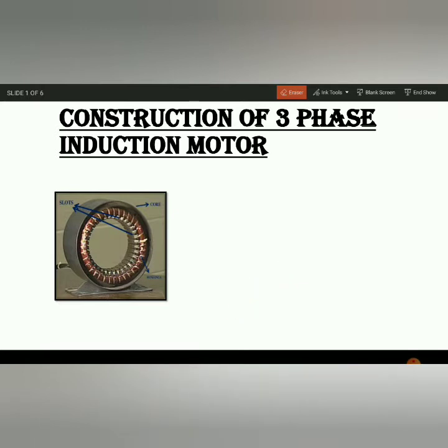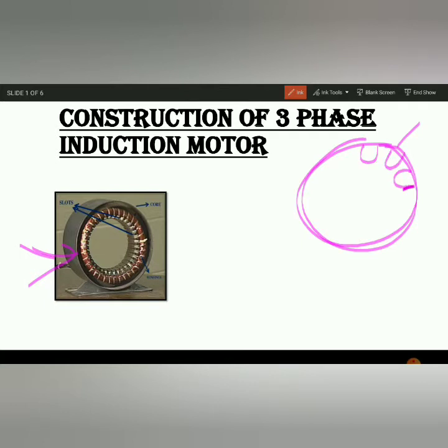And we should know what materials are used for this stator. We use materials like silicon steel and cast iron steel. The materials which have less magnetic losses, we try to use them. So coming to the stator, what is the conclusion? It is a stationary part, it has the outer coverage, and it has a number of slots. In the slots we place the three-phase winding.